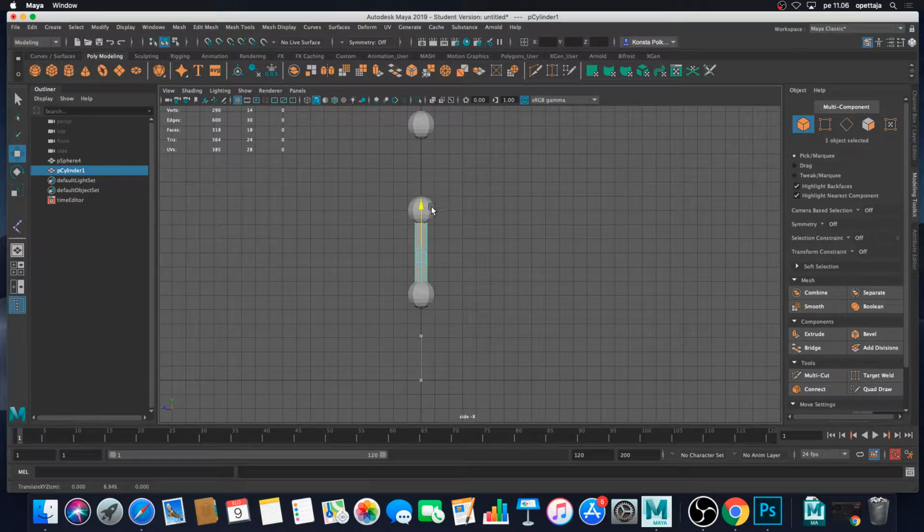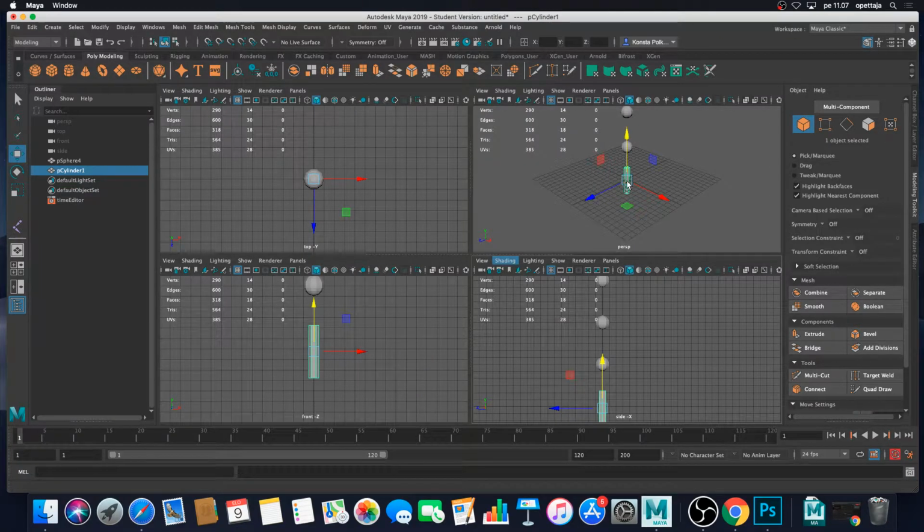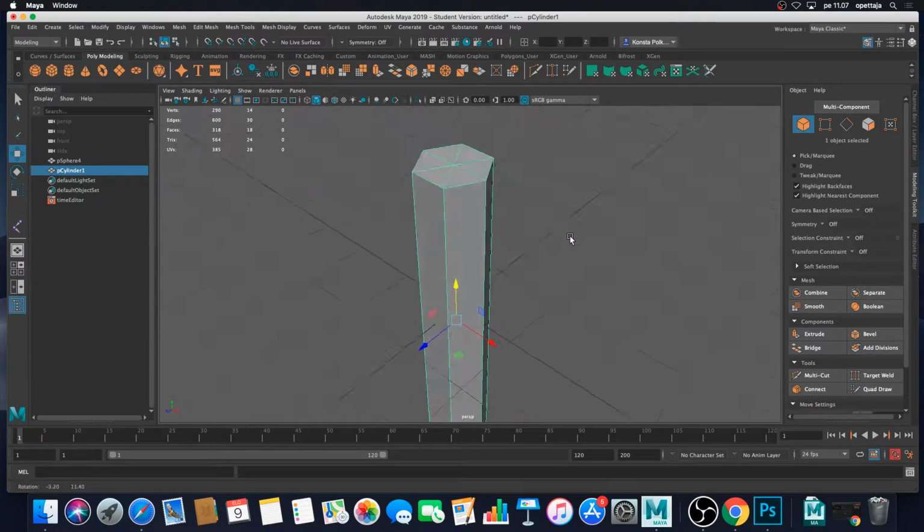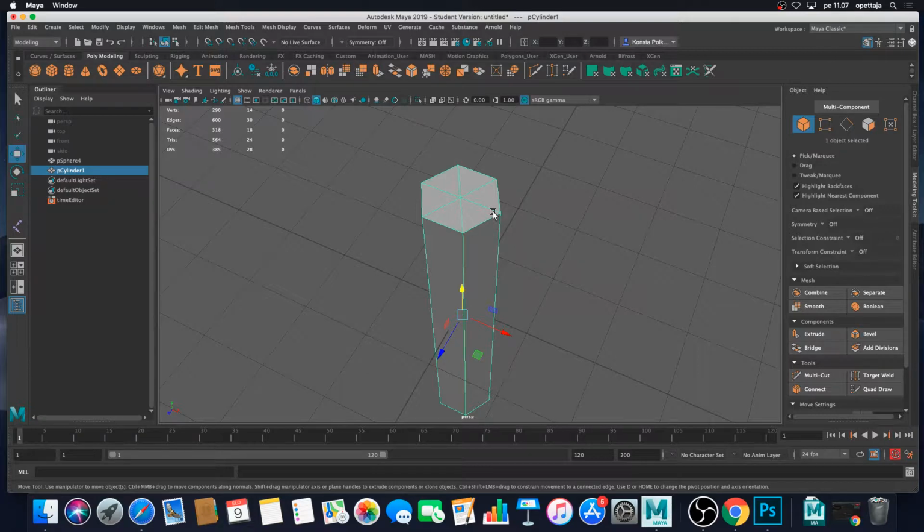And I'm going to move it upwards. So, or before I'm moving this shaft upwards, I'm keeping it here in the origin. And now I'm jumping into perspective view by tapping a spacebar. And before I'm moving this inside of the joints or the spheres, we have here triangles on top of our cylinder, and these triangles are going to be inside of the spheres, so we will never ever see them if we render. So that's why we can remove these triangles.